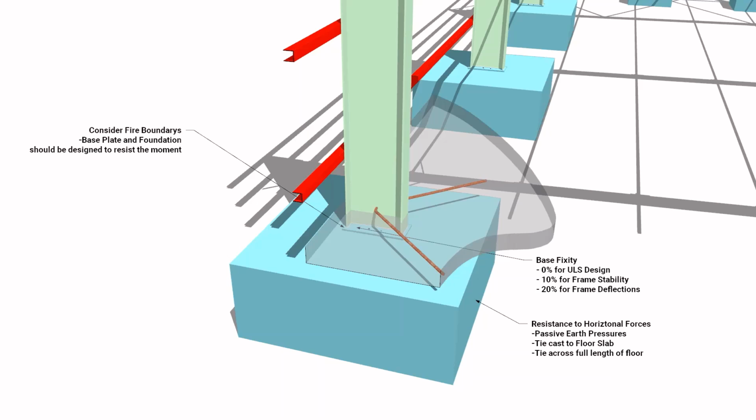in this case. So we can introduce an alternative option where we can tie back into the surrounding ground bearing floor slab, utilizing its friction capacity from its own self weight on the ground, or even tying back the full width of the frame to the opposite column. I've shown a rough detail here for tying back into the floor slab using rebar drilled through the web of the column. Details such as this will need to be coordinated with the floor slab designer and loads specified for the requirement of rebar.